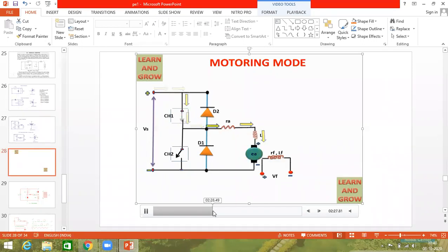So clearly you must understand. Okay, case 1 first condition. Now you can see chopper 1 is turned off. Why do we have to turn off chopper 1? Because the electric train has to approach the nearby station. Its speed has to be decreased. So what we do, we turn off chopper 1, therefore supply is disconnected to this motor, but still the motor rotates in the same direction, in the forward direction, because of the energy released by the inductor. So what is case 1? Next part. When chopper 1 is off after a certain period of time, the energy stored by the inductor is released, is de-energized, and the de-energized current will drive the motor in the same direction.